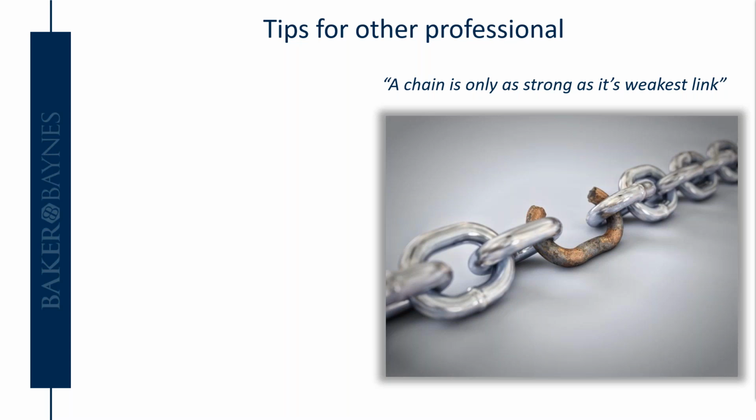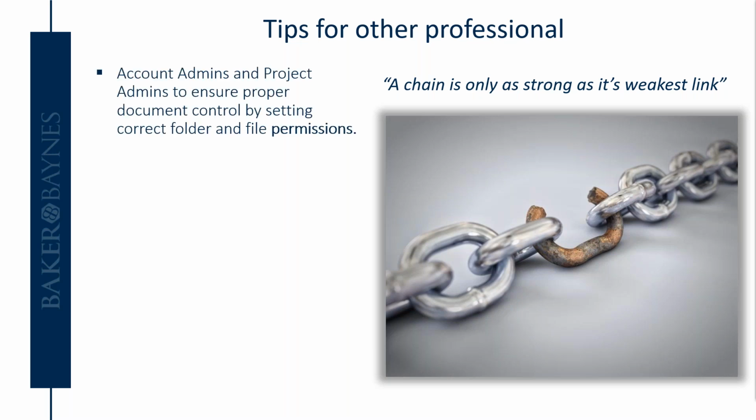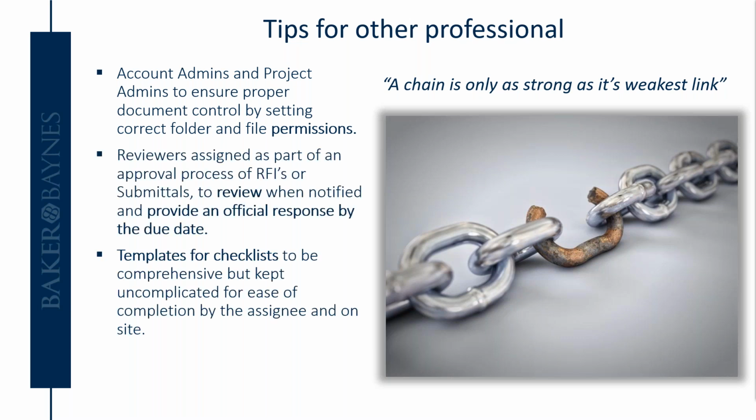Now, looking at some tips, one is that account admins and project admins need to ensure that they do proper document control. This, for instance, can be done by setting the correct folder and file permissions. So a contractor, for instance, will need permission to view or download and upload files, whereas you will only want your subcontractors to be able to view certain files that pertain to them and not necessarily be able to download or edit any files.